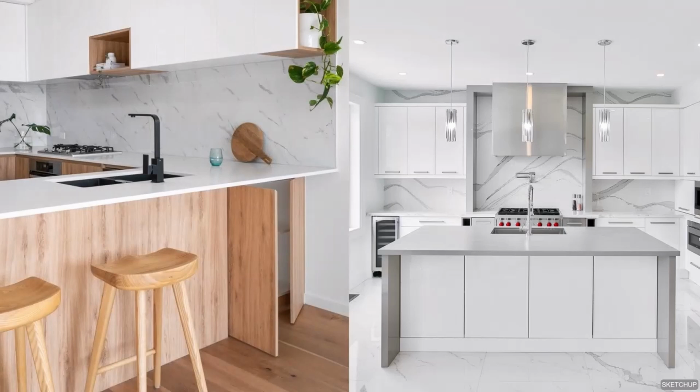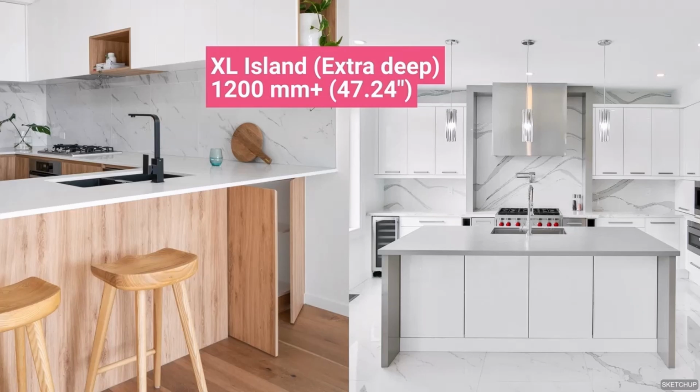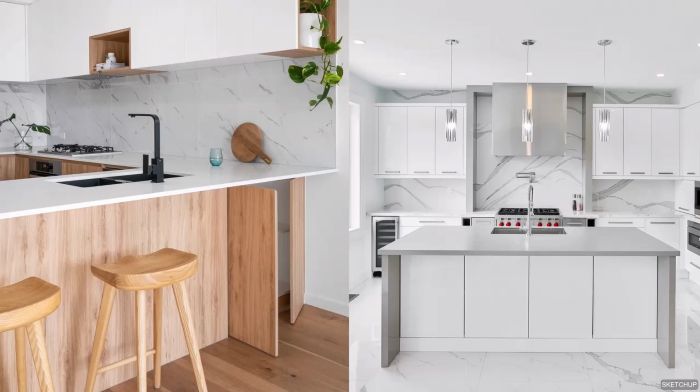If you have the opportunity to design an even wider island of about 1200mm, you can maximize the additional space in the base cupboards by integrating concealed 300mm deep cupboards that are accessible from behind the breakfast bar, adopting a push and open front mechanism as illustrated in this example.